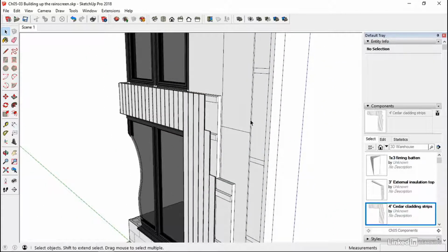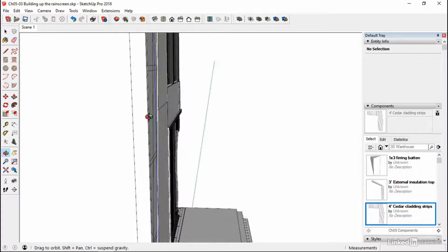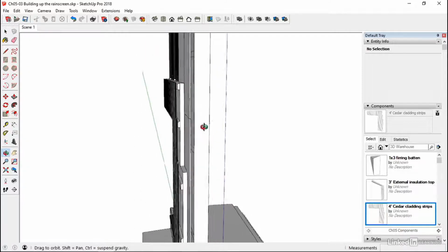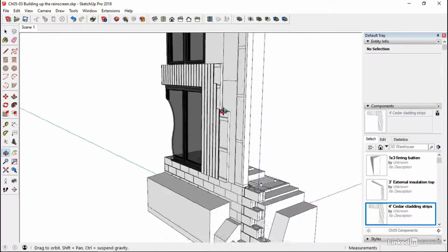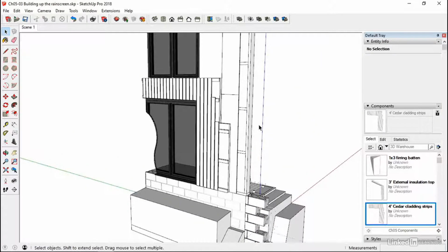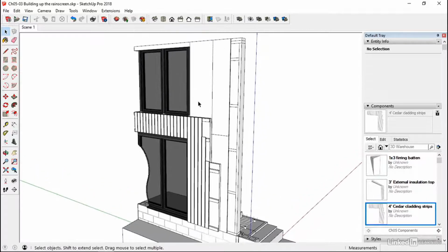2 bits of insulation, more if you need. If it gets colder, then make the frames thicker or add extra levels of insulation on the inside. You could have drywall with insulation, which is fixed via a dot and dab system. Again, that's all going to increase the U value of this wall. Okay, so that's that bit. We've got next a little bit of stucco to add on top, and then we can start looking at flashings and finishing around the openings.